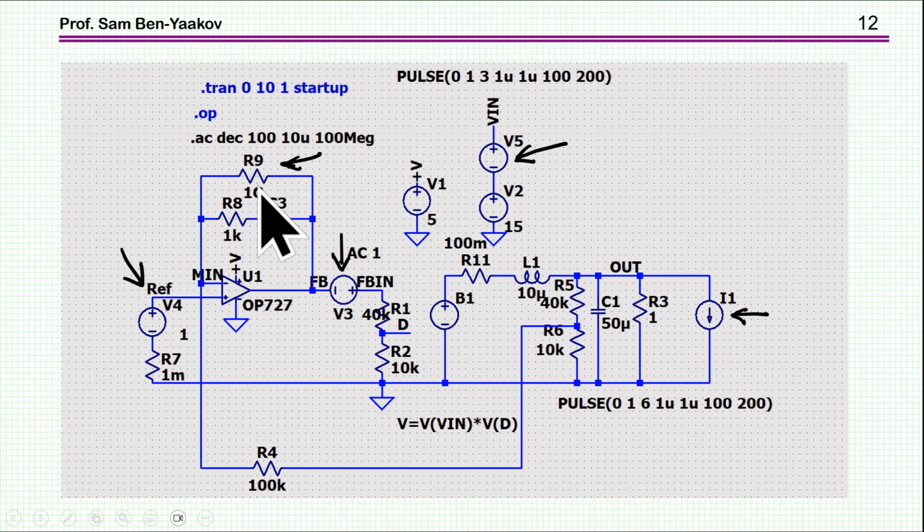And then we have the error amplifier, which has a feedback which is similar to type 2 compensator. However, I didn't do any effort to have a high bandwidth or good performance for transient, because we are only interested in the DC region. It has a large resistance here, which I'm going later on to change in order to reduce the loop gain. Now it is 1 gigahertz, and then we have here 100K, so the gain here is fairly high.